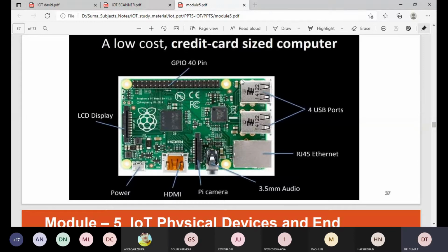These general purpose input output capabilities may include: the pins can be designed to be input or output. They can be enabled or disabled. The input values are readable: high is 1, low is 0. Output values are writable and readable. Input values can frequently be used as IRQs, typically for wake-up events.